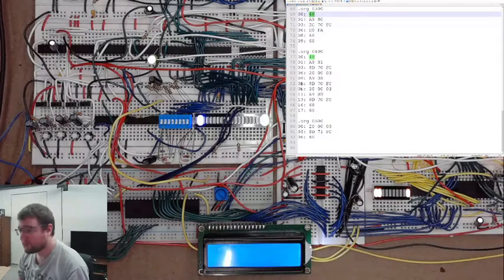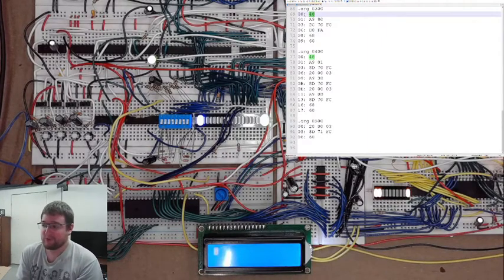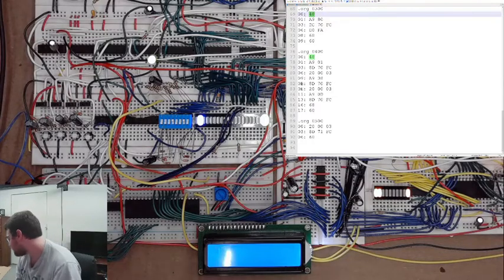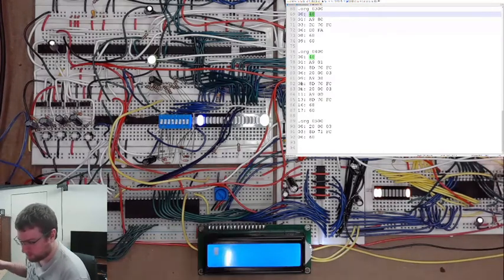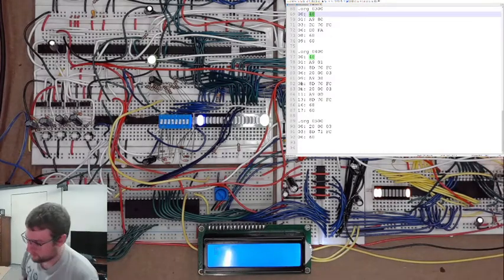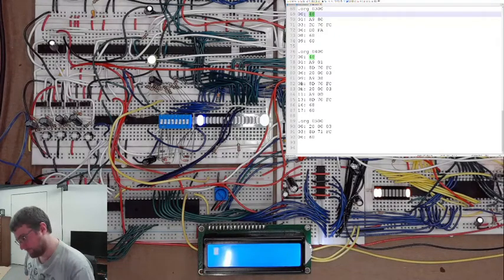I'm not sure. I don't really want to unplug it though, because then I'd have to reprogram it using the switches. So we're gonna try to make it work this way. And it might be that these clocks aren't getting enough power, in which case I can smooth that out with a couple capacitors. Let me go ahead and do that. I still need to fix the program, but this will help.